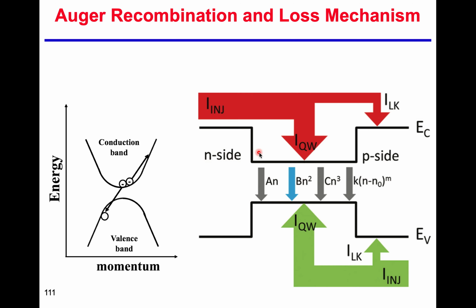Okay, so this is Auger recombination. It happens in some cases, but anyway, that shows you that the holes have a lower carrier mobility, so they will go to the heterojunction. But the electron moves very fast with higher mobility, so it is possible to have some leakage here.